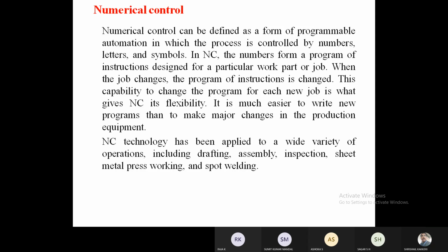These numerical control machines extend to CNC turning machines, CNC welding machines, CNC drilling machines, CNC milling machines, and even CNC painting machines. In CNC milling and some cutting machines, the XYZ coordinate control is very important. If you go for arc welding and painting operations, these will be only two-dimensional. So we are much more interested in understanding the CNC milling and turning operations in this.